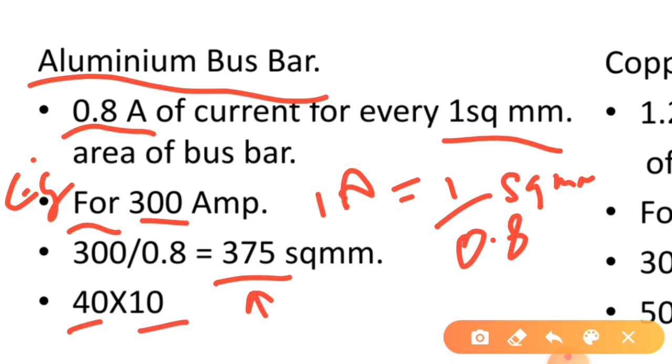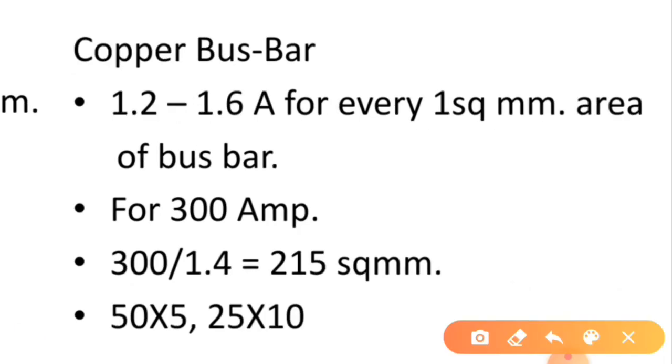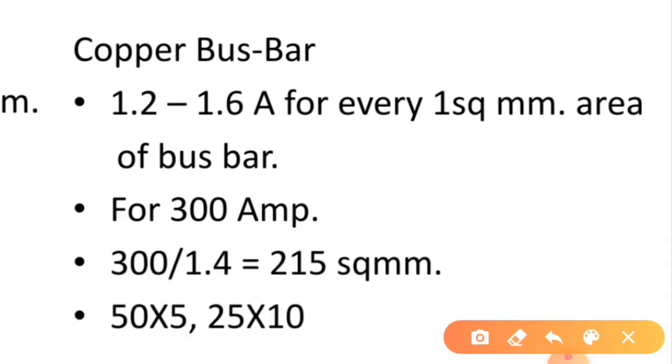And friends, here I want to make a note that this is not the perfect calculation of busbars. We take other factors like fault current, temperature, etc. But these are the thumb rules which are generally taken by control panel manufacturers for busbar calculations.